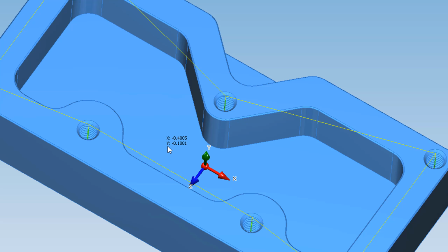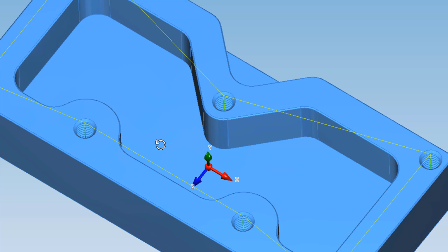Okay, and just to show one more important aspect of this interactive system, since we have knowledge of basically all the toolpaths here and the solid model, we can do things like comment out part of the drill and tap instruction. And of course, you see we've commented out the face mill and the pocket. So we can run just any individual part of our program much easier than if we were on, say, a G-code machine.